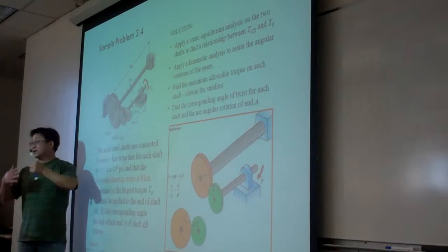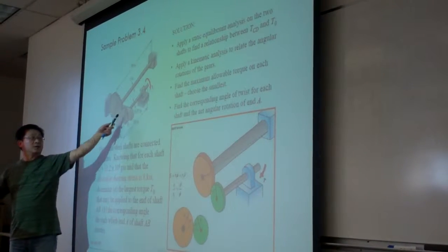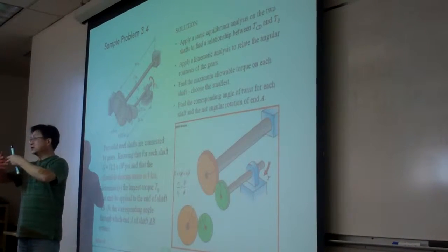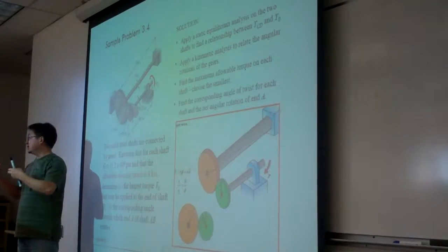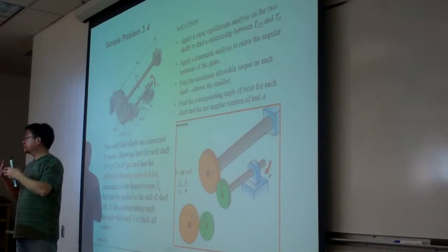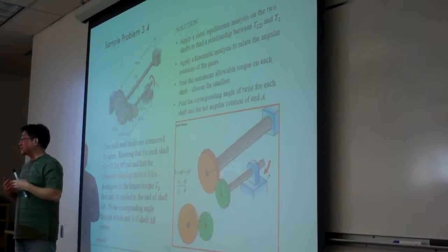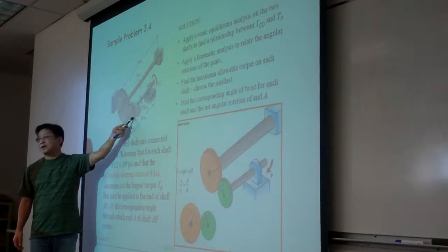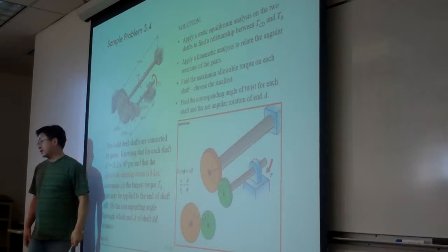To pair the gears, the teeth on one must match the teeth on the other, which means the tooth size and profile must be the same. So the smaller radius has fewer teeth, and this one has a large number.